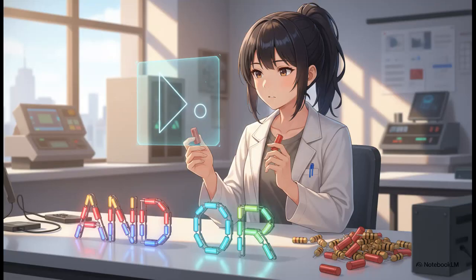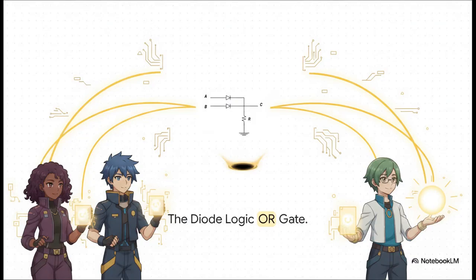The big selling point for diode logic is just how simple it is. I mean, you only need diodes and resistors. That's it. It's elegant. But that simplicity is also a huge weakness. You can only build OR gates and AND gates. You can't even make a simple NOT gate, an inverter, which is a massive, massive limitation for any real circuit. So let's start with the OR gate.